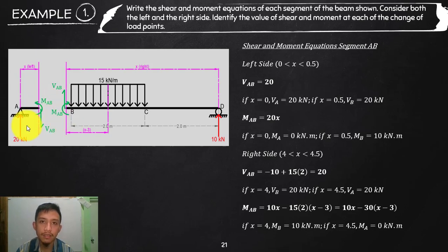to be positive. Okay, and again, what is our sign convention? A moment that will bend your beam to concave upward is a positive moment, and a shear that will try to deflect your left side going up relative to the right side is a positive shear. So for my assumption here, for the beam to bend concave upward, that should be a moment like this, which is counterclockwise. On the other side, the positive direction is clockwise, for your beam to bend concave upwards.